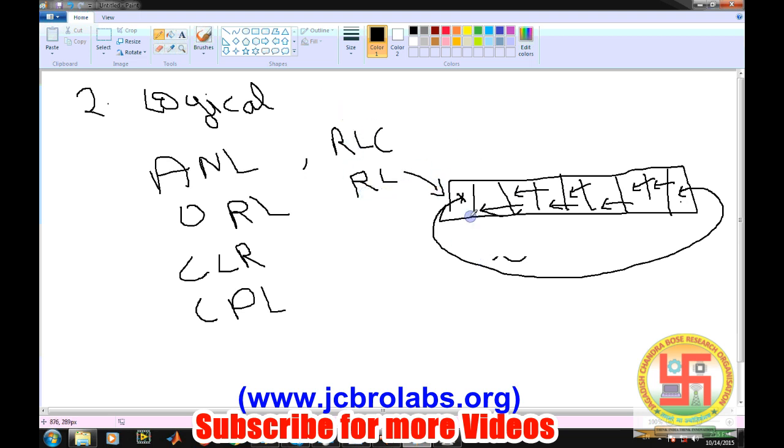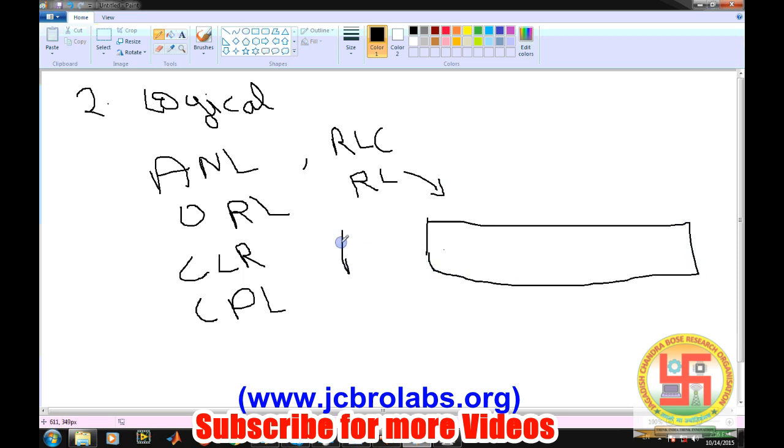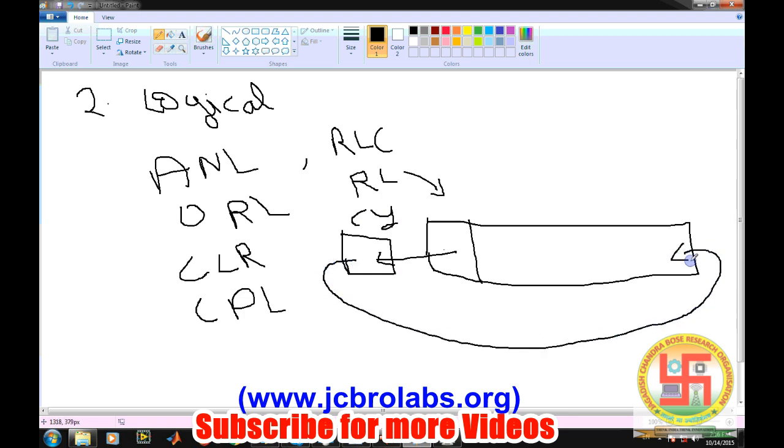And rotate left through carry: here we have the 8-bit content and the carry. The last bit will go into the carry, and whatever the content of the carry is will go into the first location, and all the bits will shift one place towards the left.